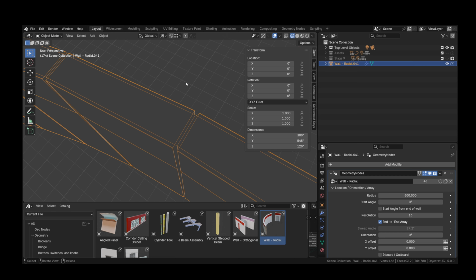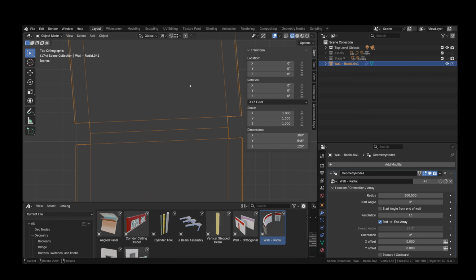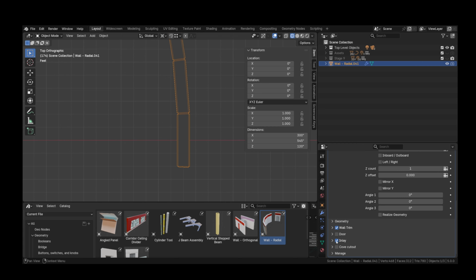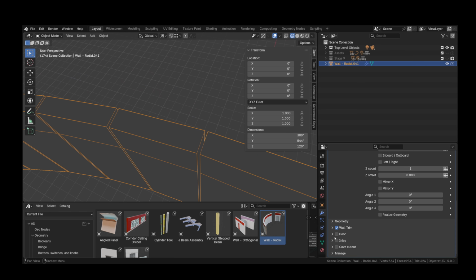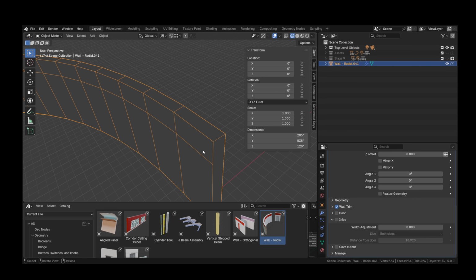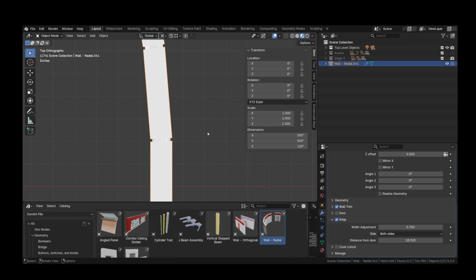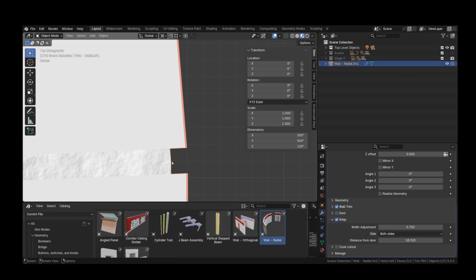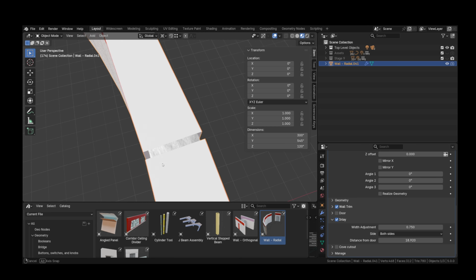If I go into wireframe here, they're butted up end to end. If I turn off the inlay, that does not change that because the inlay setting is still set to 0.75. If I change that to 0, now they butt up right up against each other. We've got 0.75 on one side, 0.75 to the other. We end up with an inlay width of 1.5 inches there.